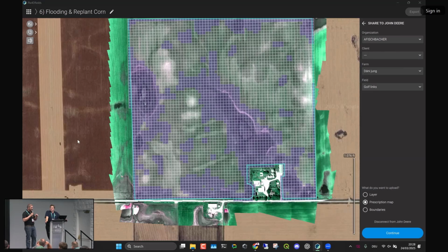So I don't want to get crazy into that topic, but that's a very important thing that you might want to consider. But yes, if you have RTK on and it's enabled, it's going to be in the photo. Now, Wingtra, Quantum, other systems, you have to tag the photo. You have to do post-processing tagging, and you have to have a base station. So there are some things that you have to know about that, okay?